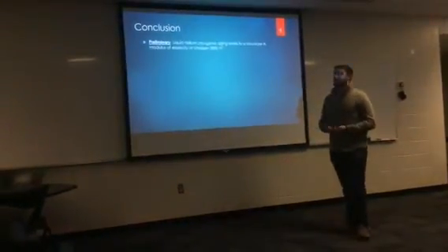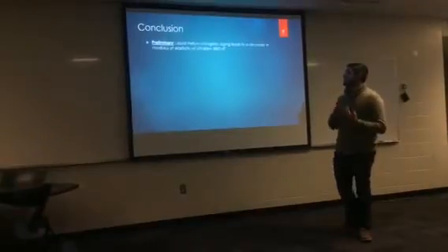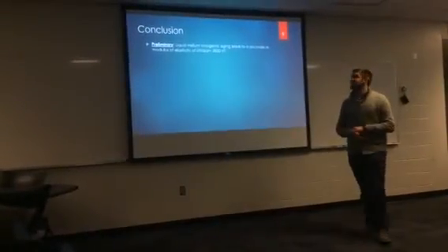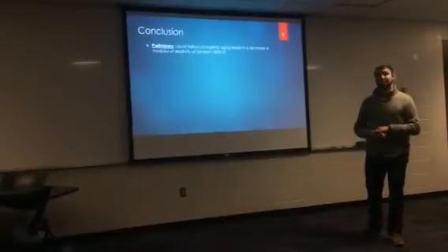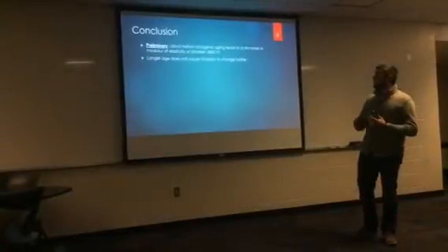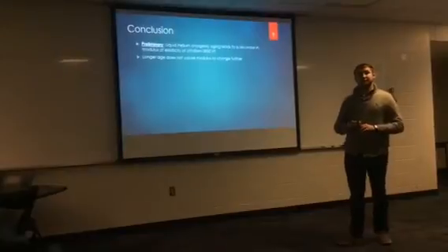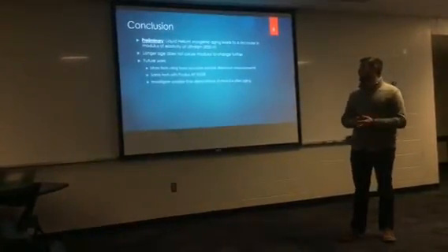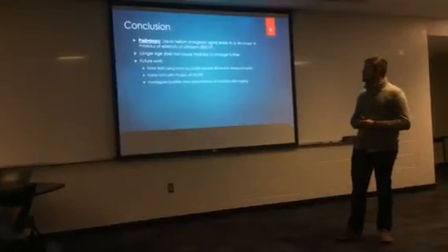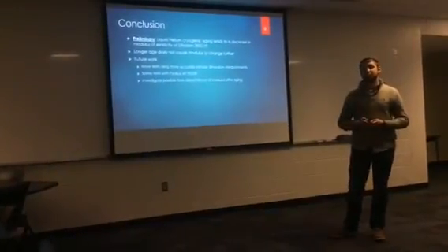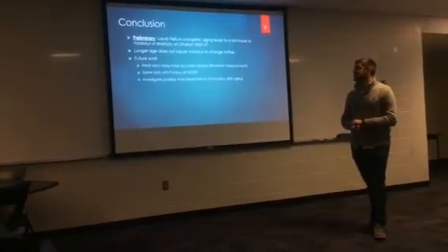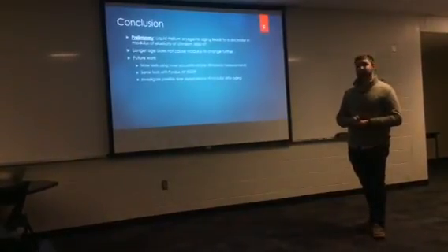Now, in conclusion, as a preliminary study, we've shown that liquid helium cryogenic aging leads to a decrease in the modulus of elasticity for ULTRALAM 3850HT. Longer aging does not cause the modulus to change further. This is another study that we'll be looking into, as well as some other future work using more accurate sample measurements, the same test with another polymer, Lux, and also we want to investigate the possible time dependency of the modulus after aging. Thank you.